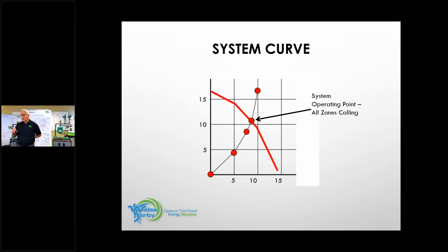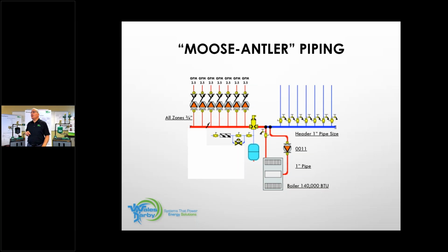We start to shrink our delta T, okay? Take advantage of the universal hydronics formula, take advantage of that head loss formula, make sure you're sizing your circs right. Okay, so the moment we've been waiting for, this is our favorite part, troubleshooting.